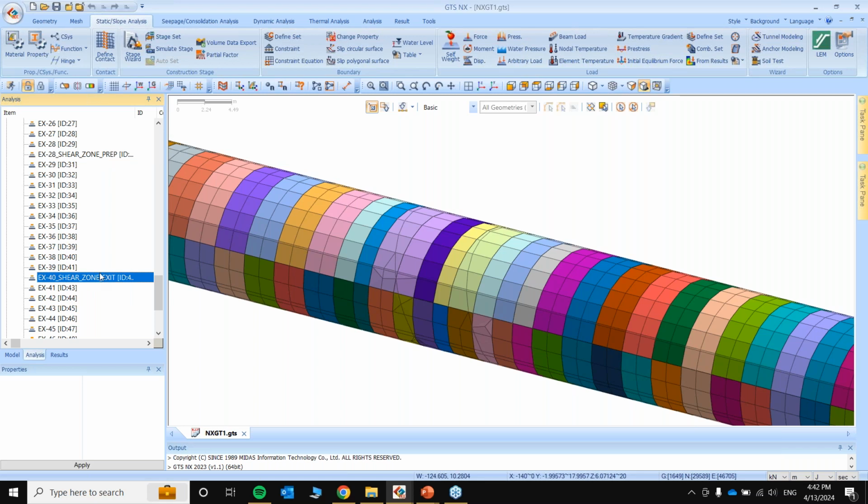So just because the shear zone is there, it does not essentially mean that only at the material boundaries you will get the deformations or plastic failure. It can happen even in areas close to it, depending on your ground stress scenario. So if, let's say, this overburden instead of 45 meters had been something like 700 meters or 500 meters, you could have seen a complete collapse in here with these kinds of support conditions, because the stresses would have been that high.